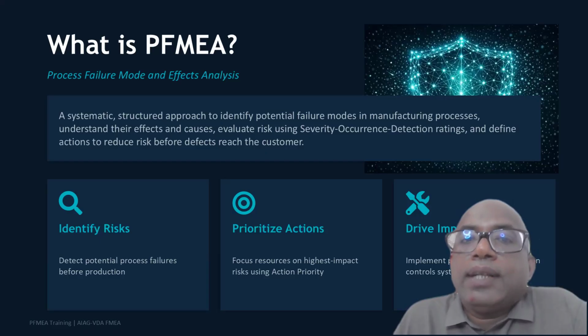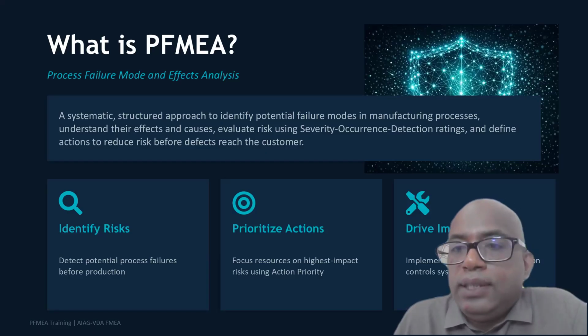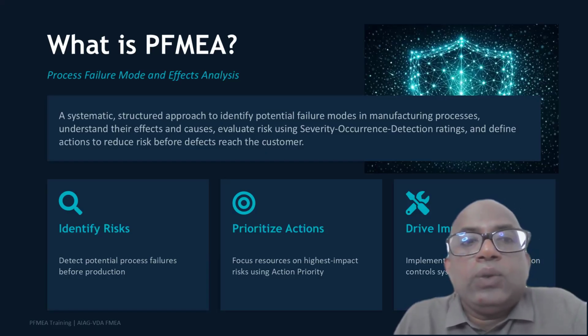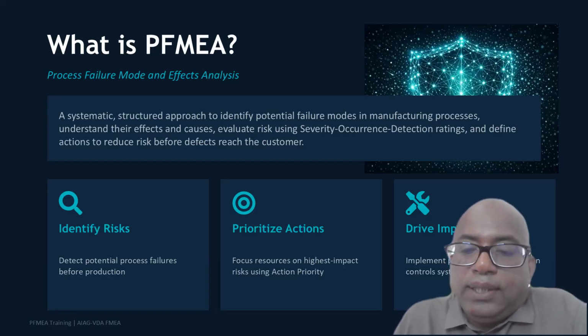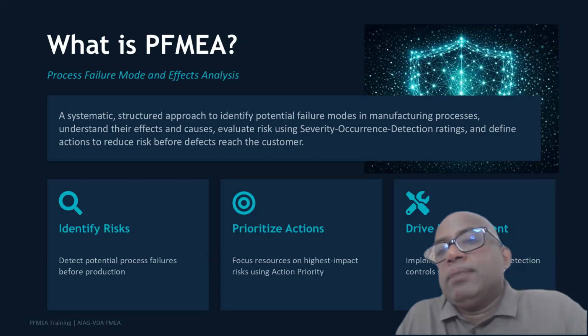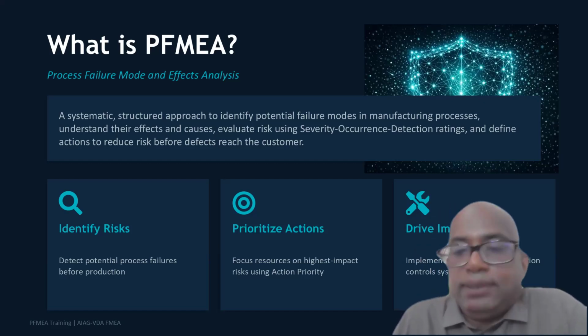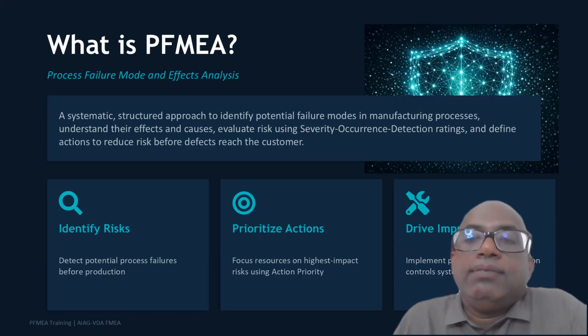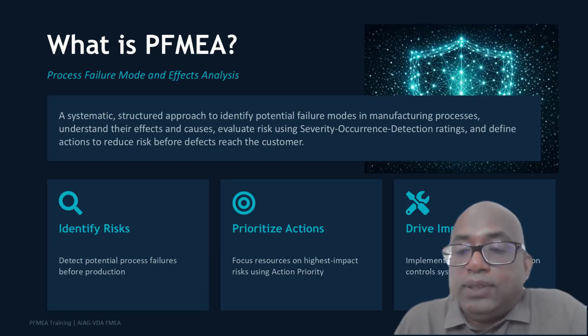Then evaluate the risk level using severity, occurrence, and detection ratings, and define actions to reduce the risk before defects reach the customer.